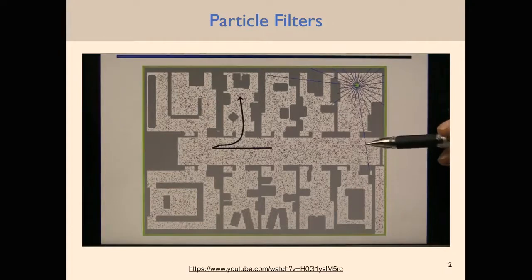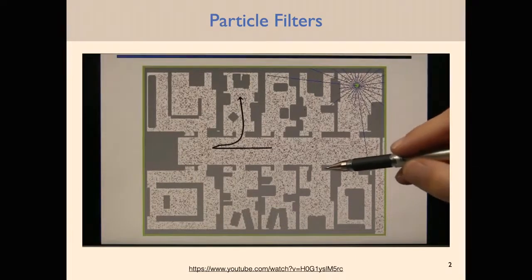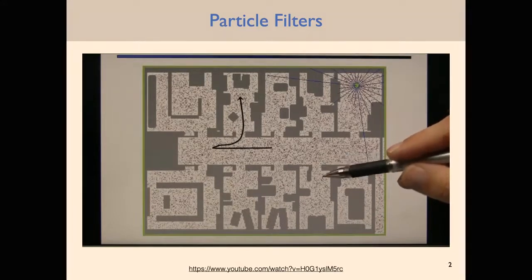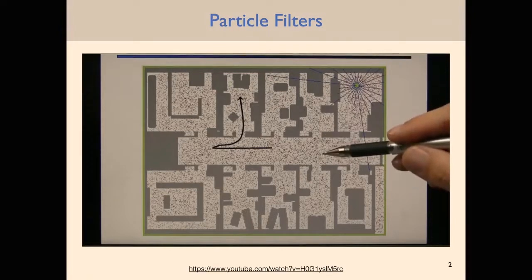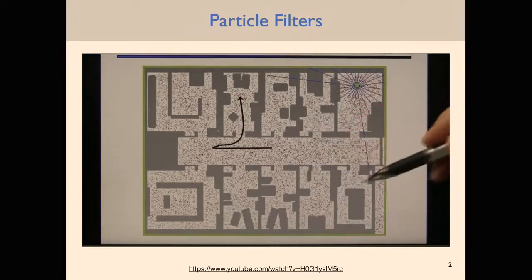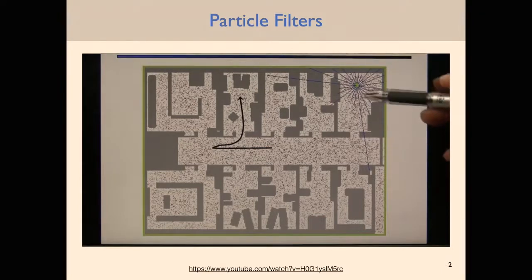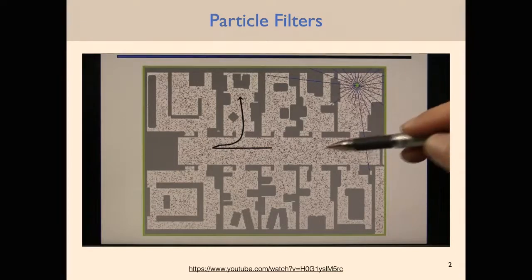Now, the key thing in particle filters is the representation of the belief. Whereas before we had discrete worlds, like our sun and rain example, or we had a histogram approach where we cut the space into small bins, particle filters have very different representations. They represent the space by a collection of points or particles. Each of these small dots over here is a hypothesis where the world might be. It's a concrete value of its x location and its y location and its heading direction in this environment. So it's a vector of 3 values. The set of all those vectors together form the belief space. So particle filters approximate the posterior by many, many, many guesses, and the density of those guesses represents the posterior probability of being at a certain location.